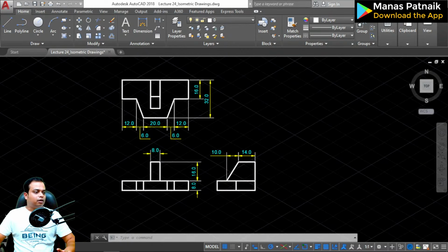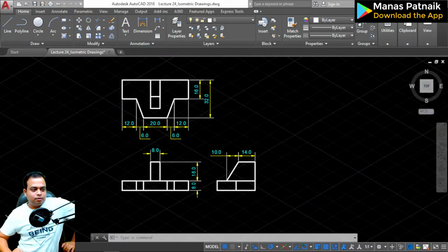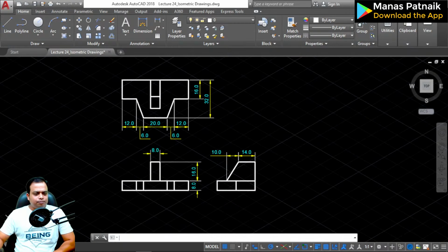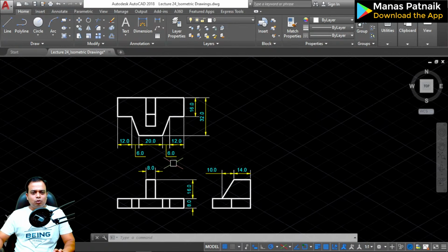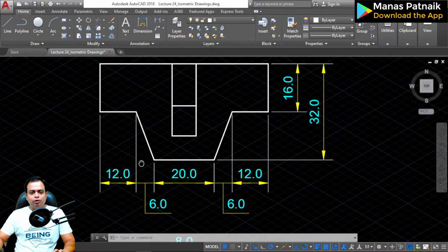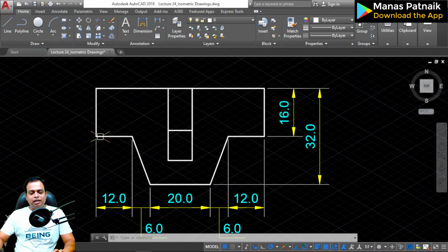Okay, so how do we proceed from here? This is going to be simple. Watch. The first thing to do is to create this in the top view, okay, or in the top plane. You'll soon realize this. So where should we start from? You can actually start from this point and then move towards the left, behind, right, in front, and left. Okay, let me tell you why. Because these are sort of inclined edges, and to make them you need these two corners as specific locations.